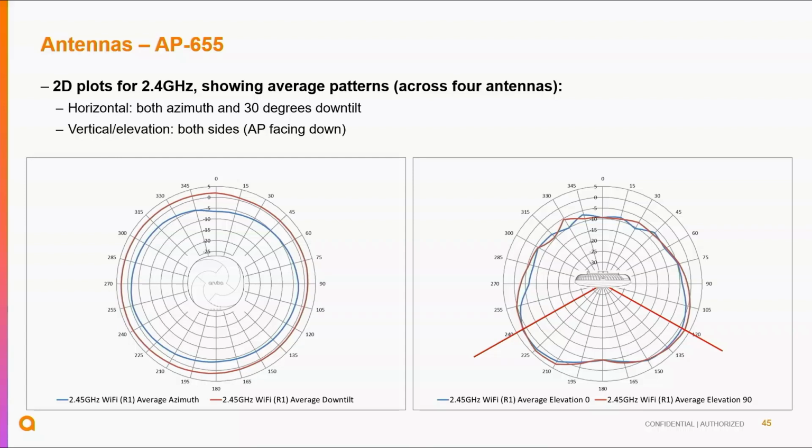If you want to maximize that, you're better off using dipole antennas, stick antennas, and using external antennas on the AP, because those have a true omnidirectional pattern around them. And if you do deploy those antennas, don't deploy them the way they've been deployed here, okay? Because you want those donuts to be like that. You don't want one like this and the other one like that. It's just weird. Are there any here? I don't know, but they're in the other rooms at least.